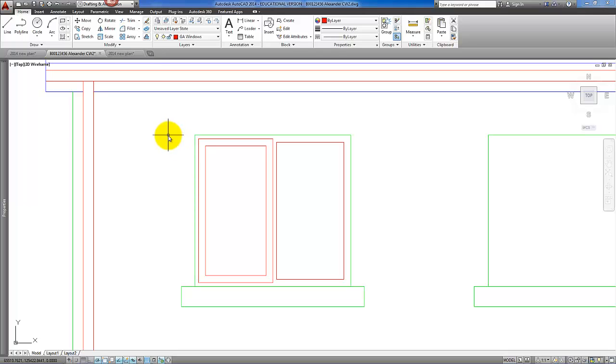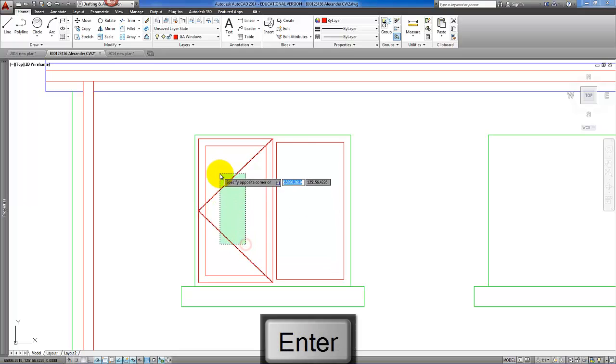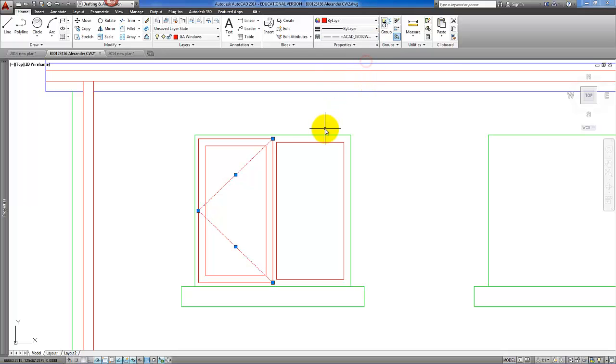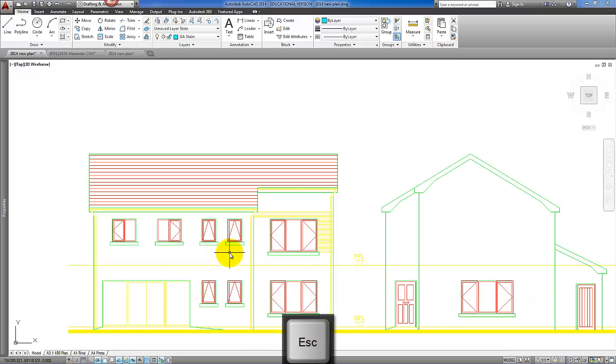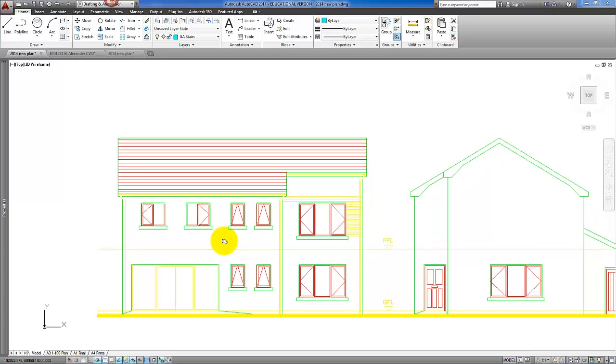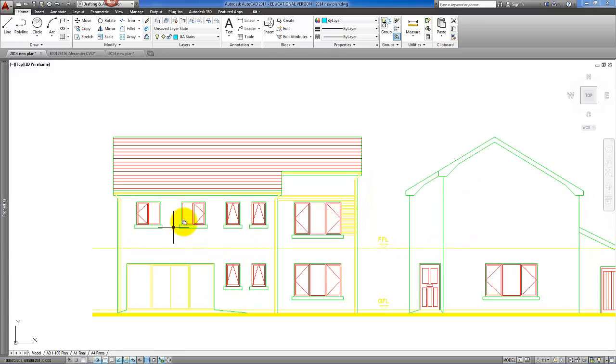we need to know how the window might be hinged. So we can draw a line, another line to indicate that, and we can apply a dashed line to that. And obviously then that needs to be able to print out at the right scale. So effectively, if you look at the elevations on Blackboard, you can copy more or less the same style of windows that are there.